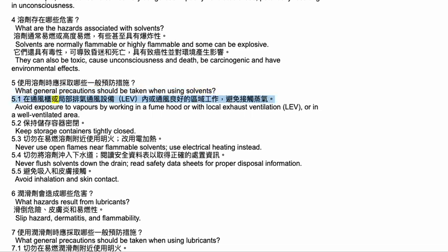5.1 Avoid exposure to vapors by working in a fume hood or with local exhaust ventilation or in a well-ventilated area. 5.2 Keep storage containers tightly closed. 5.3 Never use open flames near flammable solvents.